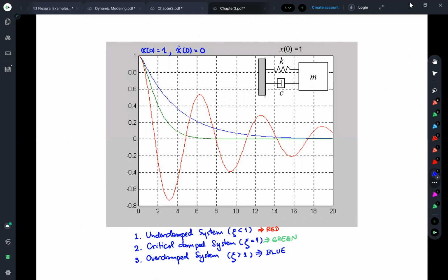If we look at the mathematics, the solution of the green and the blue, we found that if you have too large a value of damping, more than critical, the system will be very inert. It has very slow movement because your damping is very, very large. And that's why they go to zero slower than the green.